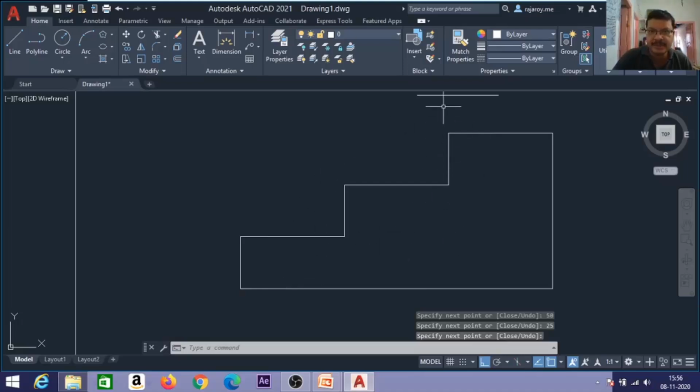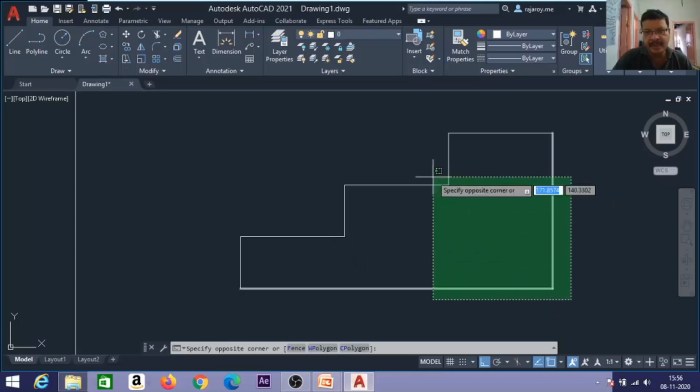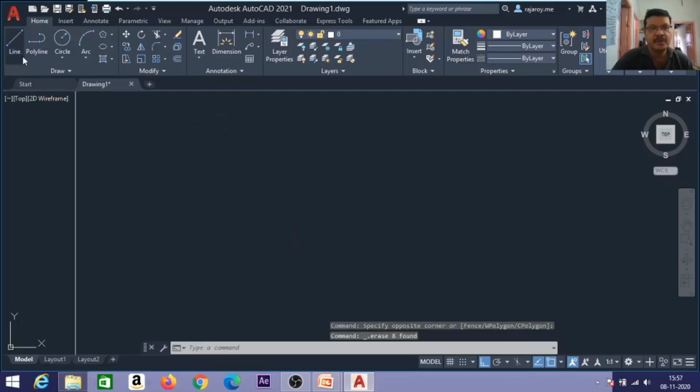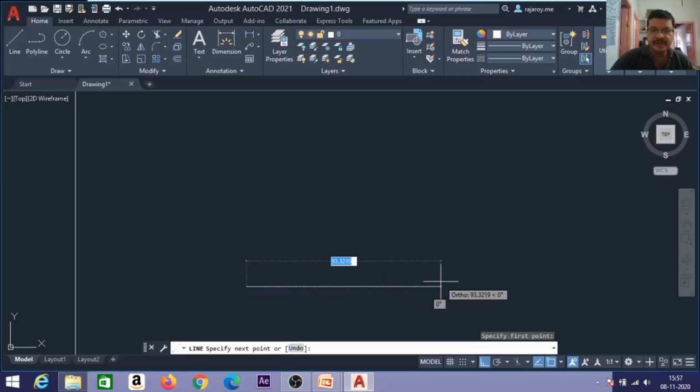Okay, to draw these steps drawing, which coordinate system have I adopted? Relative or polar? Think over. So here I have not considered either polar or relative or absolute. Another easy technique is there. I'll explain that now. Go to the line command. Somewhere here you pick the initial point. After that, use the F8 function key. Then you will get one option here.